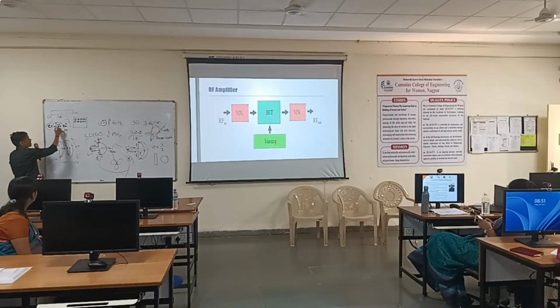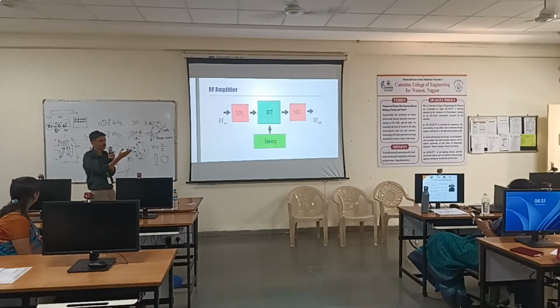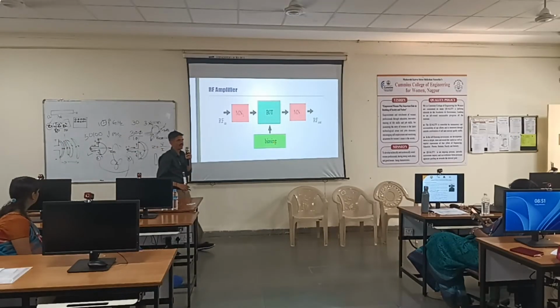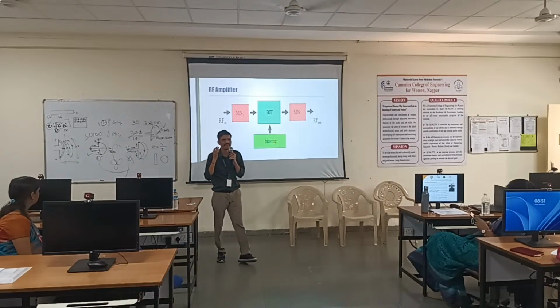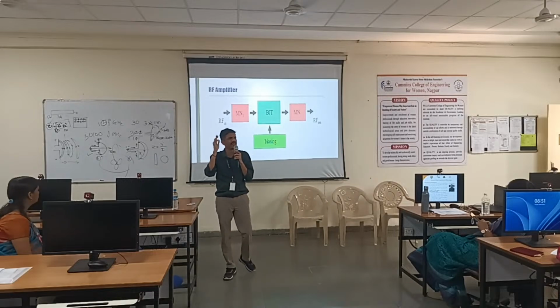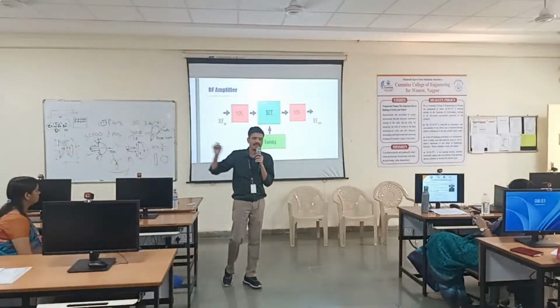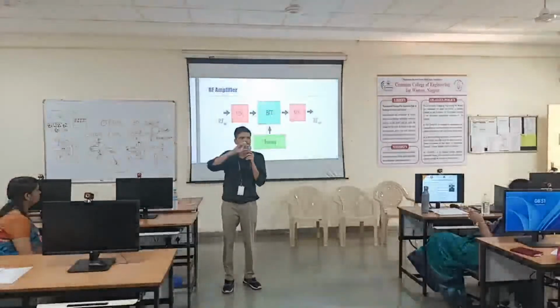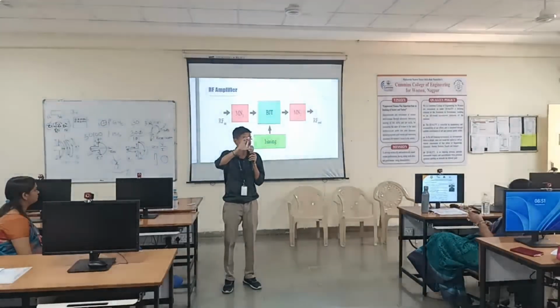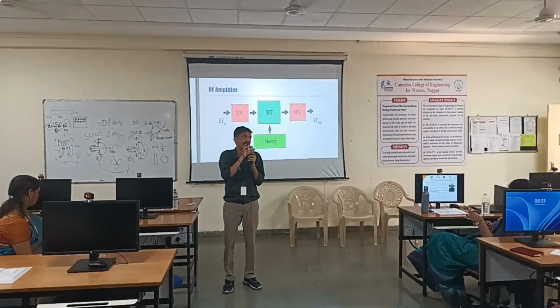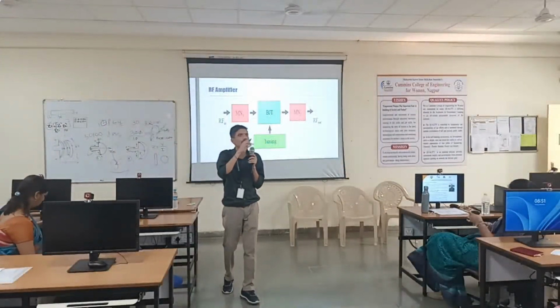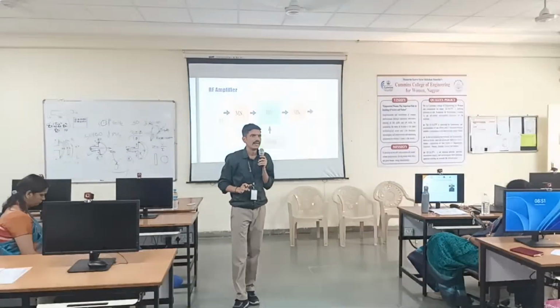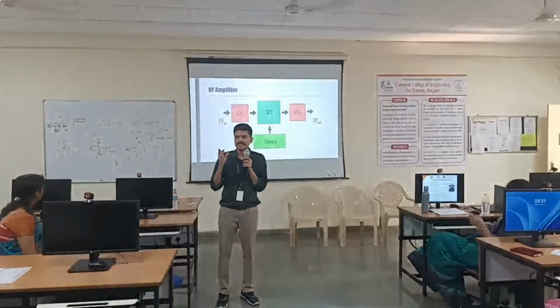So this is the first section impedance, this is the second section impedance. I can show you once I open the tool. I can give any arbitrary numbers, let us say 50, 10, 100, 10, 100,000, whatever it is. I will calculate that number and put the impedance of that line. That line impedance should be that much. That is the lambda by 4 line impedance, and length will always be lambda by 4. It is independent of frequency.